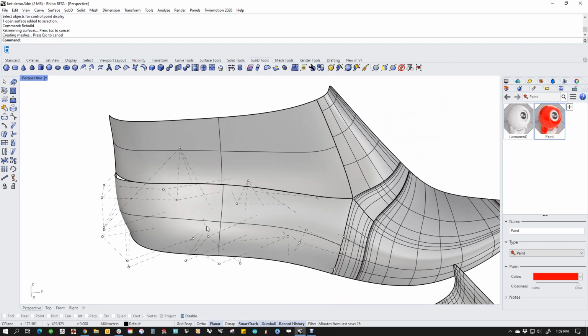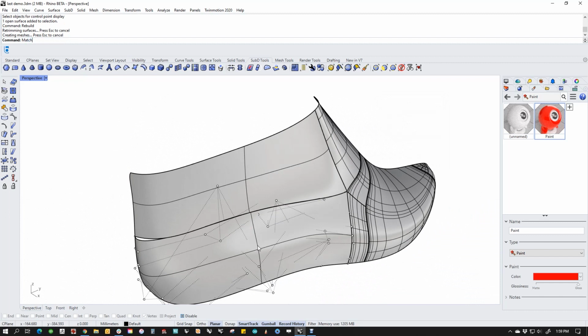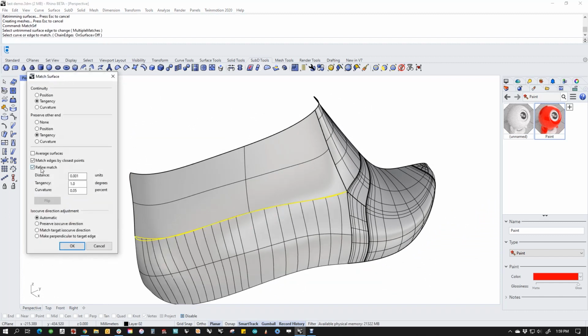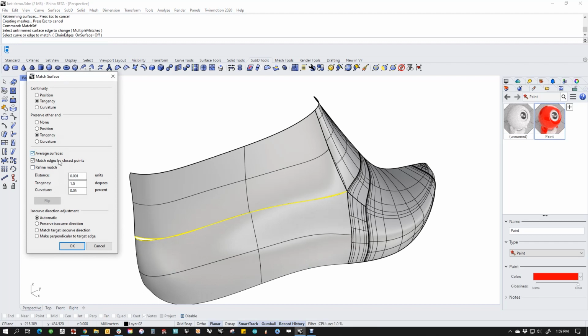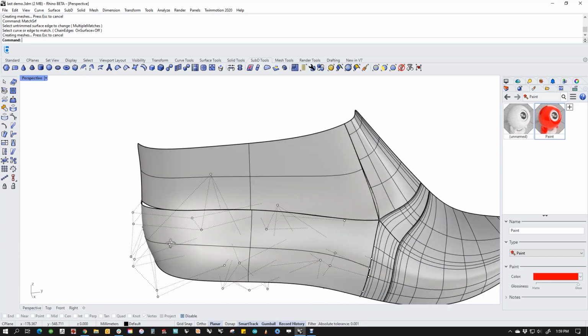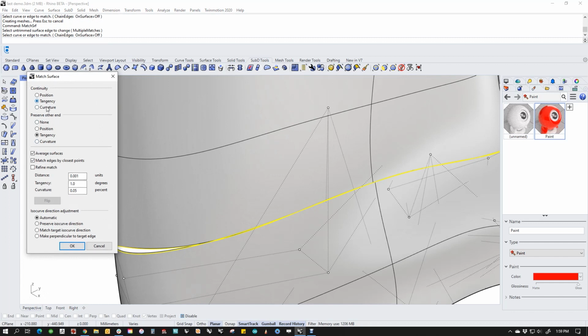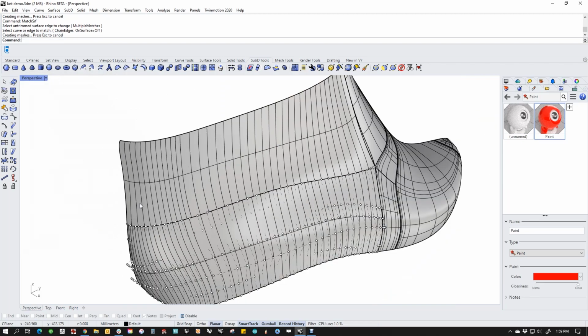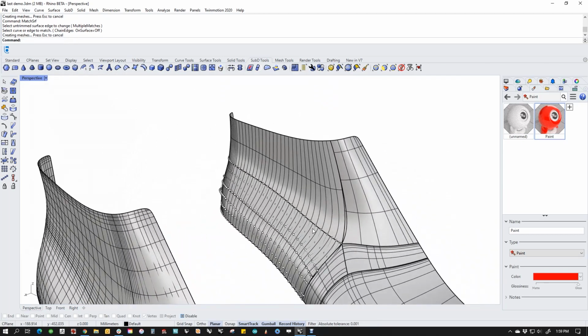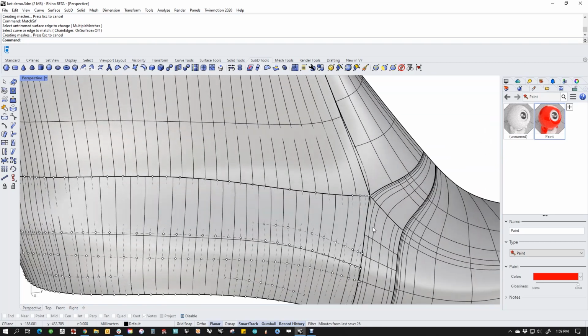and end up with two single span surfaces, then I could come in here and match surf and have the basis. I'm not going to refine this. I'm going to average them. It doesn't quite have enough points in order to be able to make that match. So let's, actually, let's not preserve the other end. Let's go ahead and refine it. And that would be how we would end up with a cleaner match based out of those.